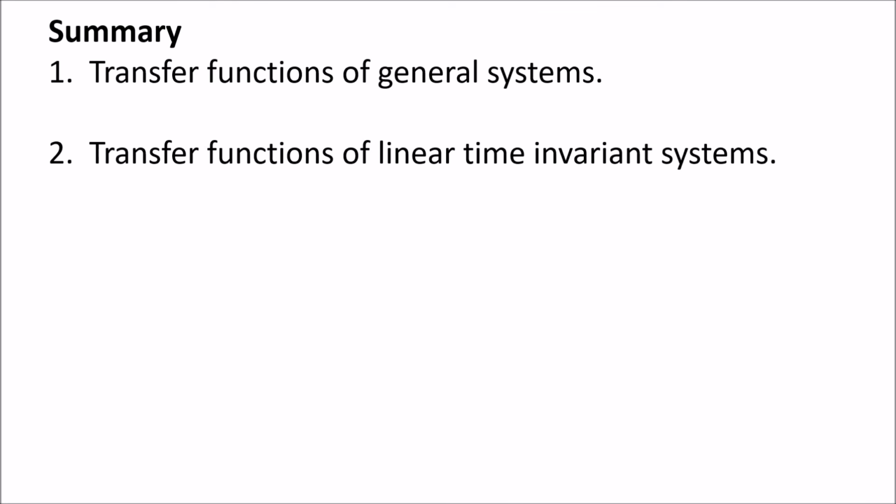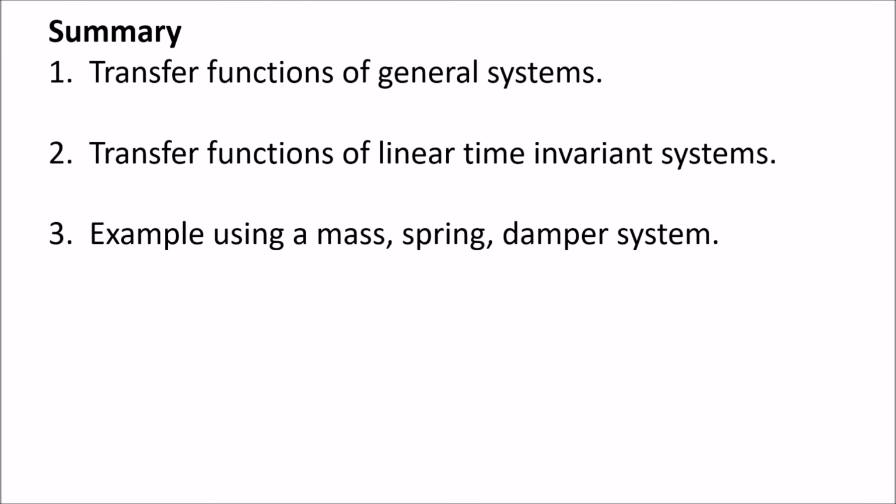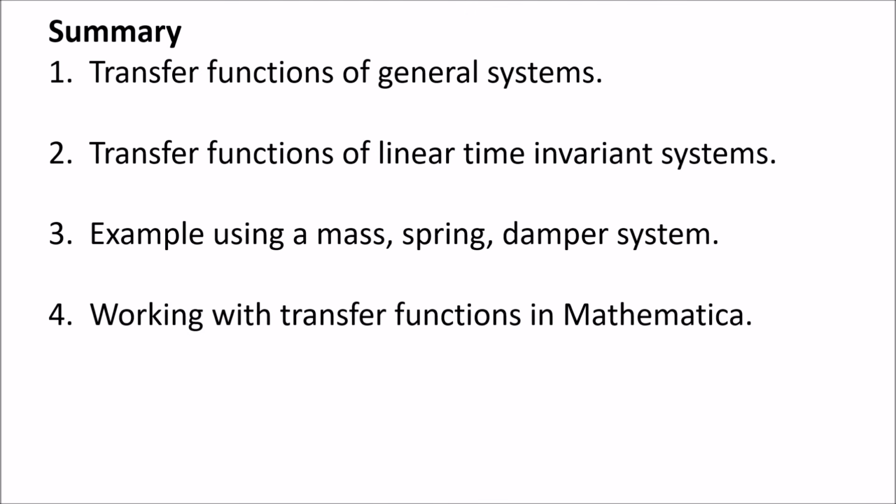And we looked at how to actually compute the transfer function of a general LTI system. We then looked at an example using a mass spring damper system, which is a pretty classic LTI linear ODE system, and we saw how you can get a transfer function between a given input and a given output of that system. Then we looked at some of the implementation of how to work with transfer functions. We first looked at using them in Mathematica, and we saw that really this is just using Laplace manipulations, because a transfer function is really just a Laplace transform of the output over the Laplace transform of the input.